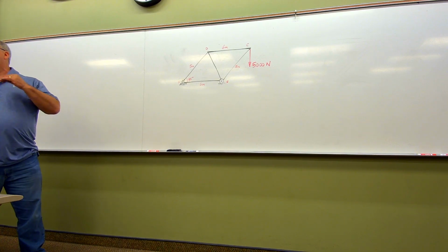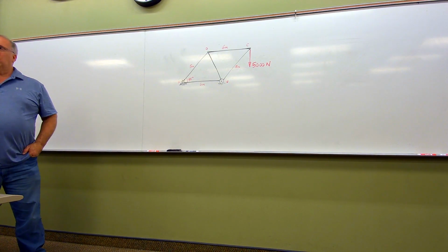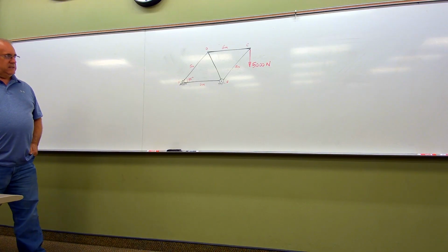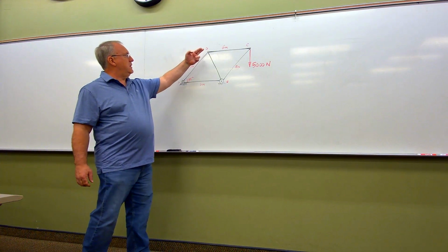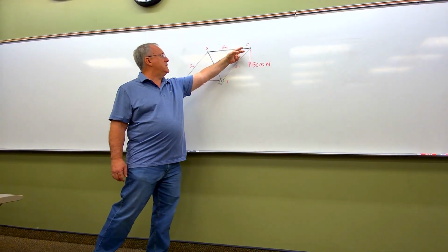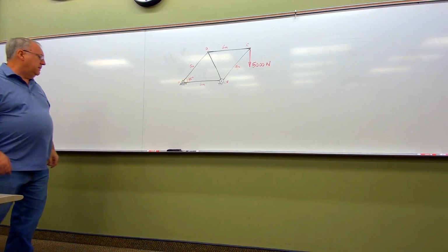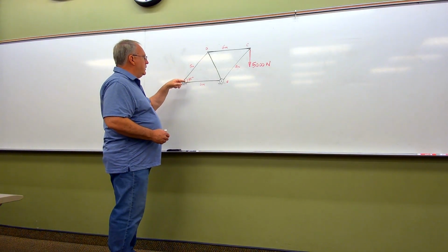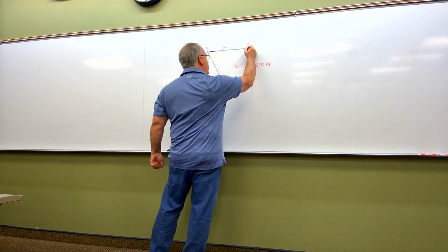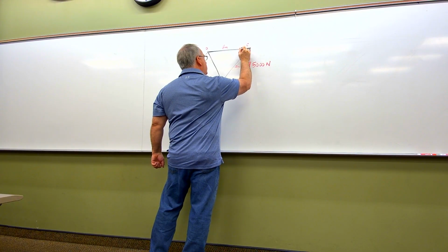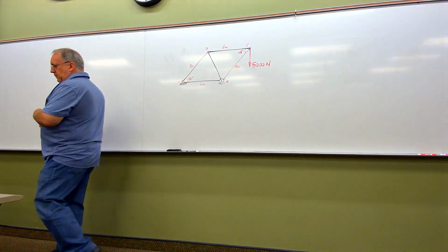But again, as we'll see when we get there, they literally are the same thing, just cloaked differently because they look different. In this truss, the dimensions tell us something important. We've got a 5-meter leg here, a 5-meter leg here, a 6-meter leg here, and a 6-meter leg down there, meaning that this is a parallelogram. Important because if we know that this is a 45-degree angle here, and this is a parallelogram, then we can also assert, even though it's not in the original diagram from the book, that this too is a 45-degree angle right here, because of the nature of the parallelogram.